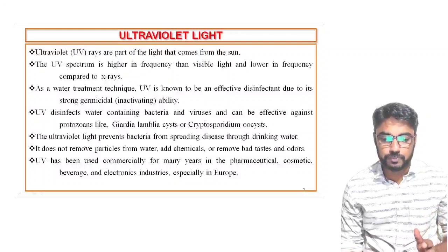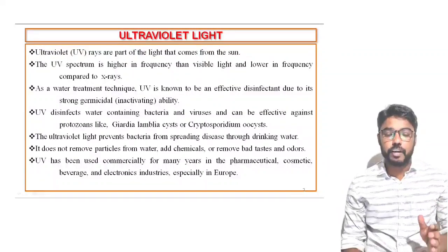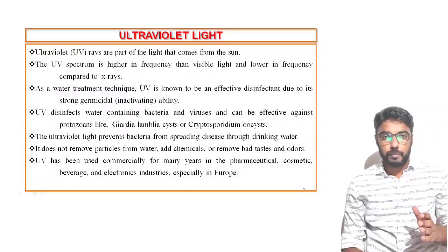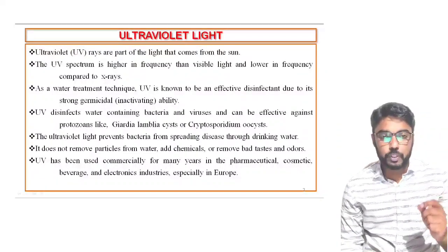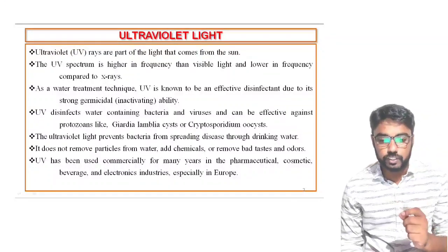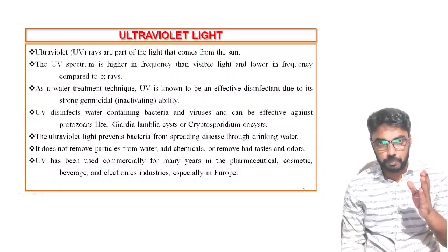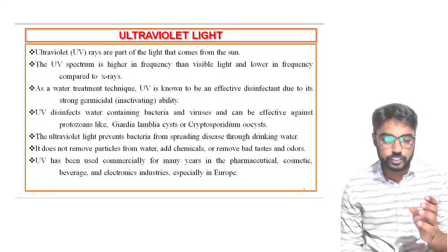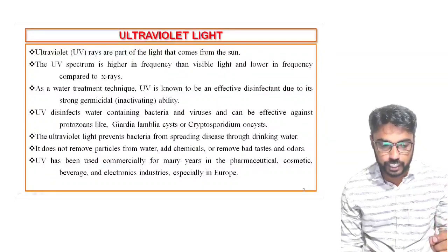This ultraviolet light prevents bacteria in the water, and it can prevent the spreading of bacterial disease through drinking water. And it does not remove particles from the water. This UV light does not remove the particles from the water. It only has germicidal activity.